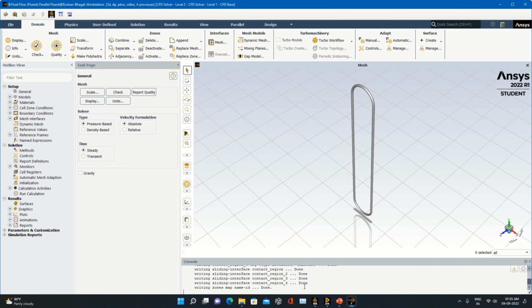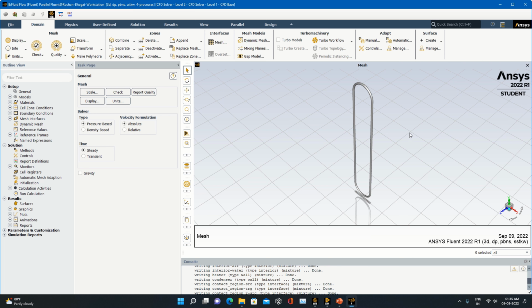This is the thing you have to remember when you are proceeding. First thing will be to visualize the object as per the requirement. Then we have to select the transient model, and the gravity has to be specified in the negative direction of y.